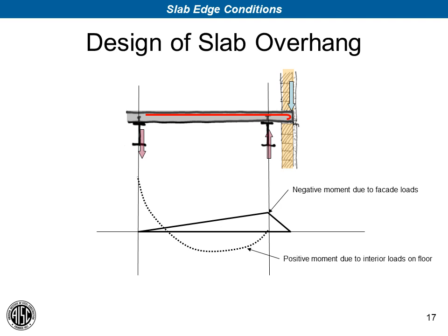I'm not sure I understand the question. Extending the slab into the wall. Perhaps the question asker is looking for some reinforcement going into the wall, providing fixity between the slab edge and the wall, is the way I understand it.